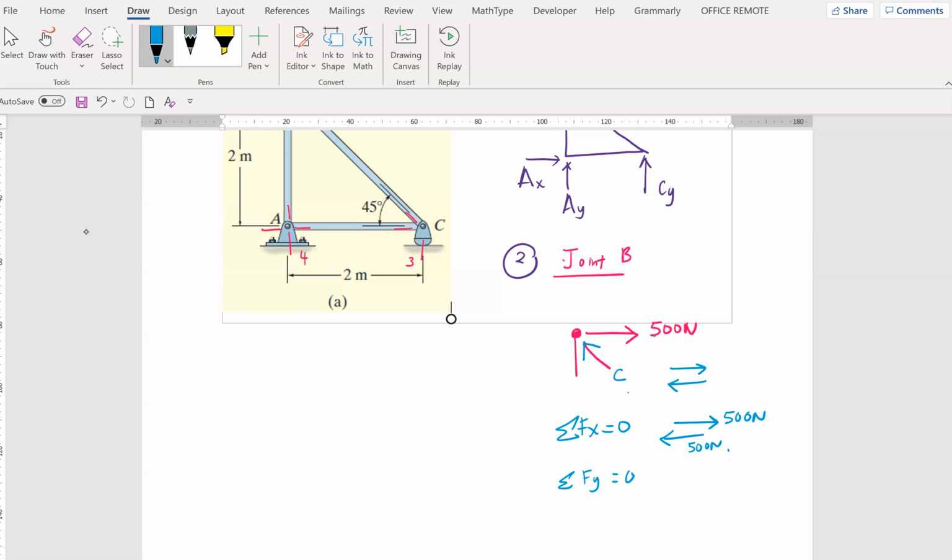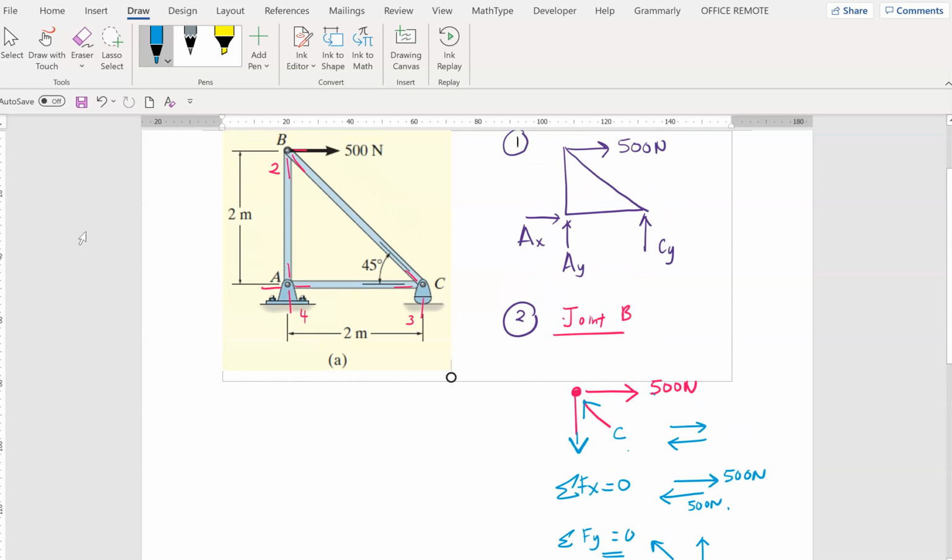Okay, now let's look at this fella. Fy equals 0. So if you have something which is pointing something like that, when you resolve it, it will be vertical upward, right? So definitely this partner will be pointing downward. So you have to name them. Don't just simply give any names that you like. So this would be from point B, right? From point B. So this would be BC and this would be BA. Sorry, I can't write. Oh, this is BA. BA. Okay, no problem.